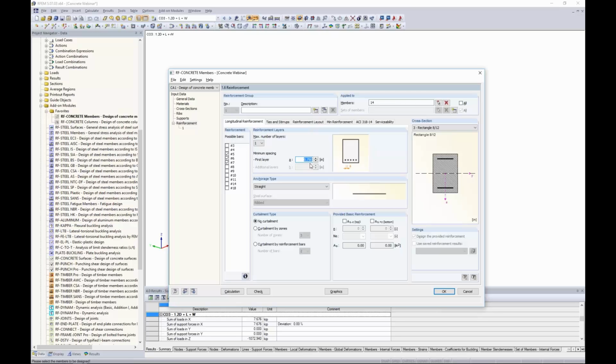I have no idea what the diameter of the aggregate is. As an engineer you might know that information, so of course you'd want to take that into consideration, but we do not have an entry for that in the program. 1 inch will probably be controlling here because I have bar sizes under 1 inch in diameter.